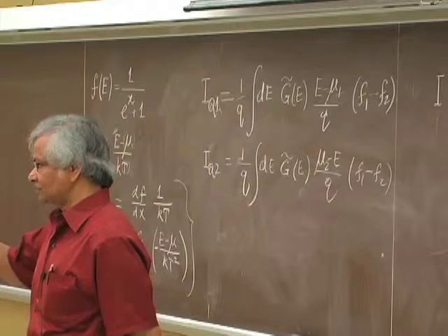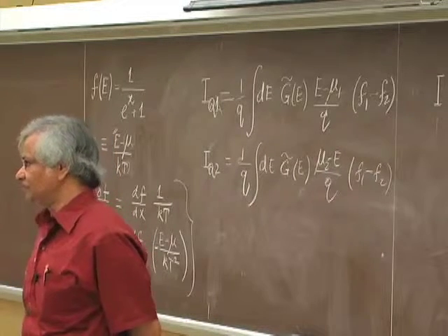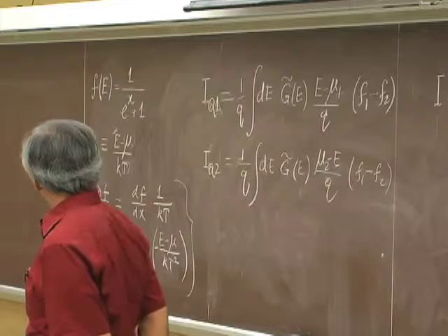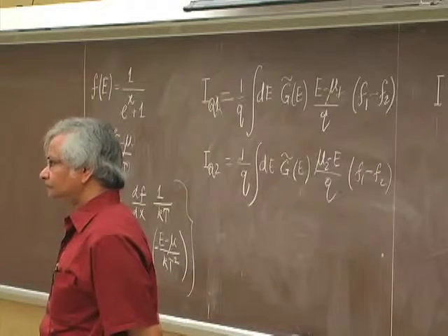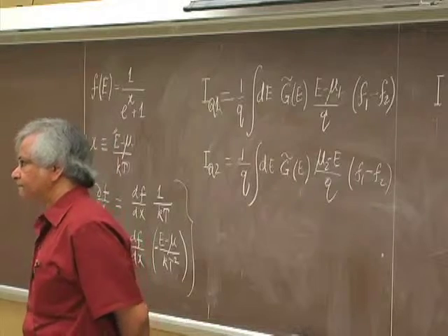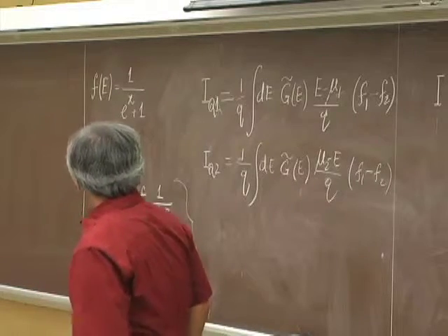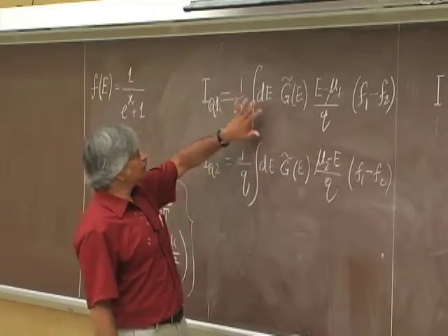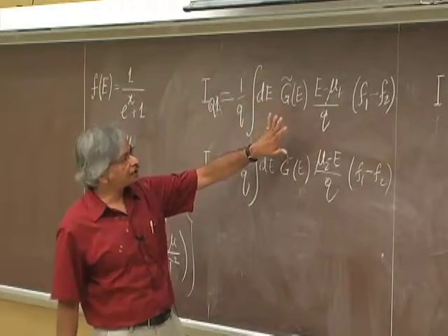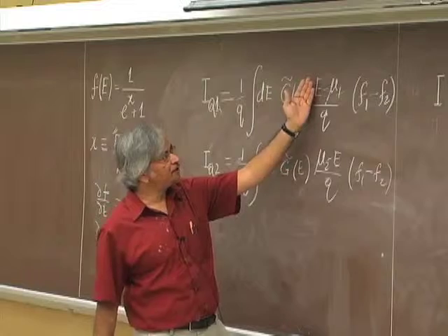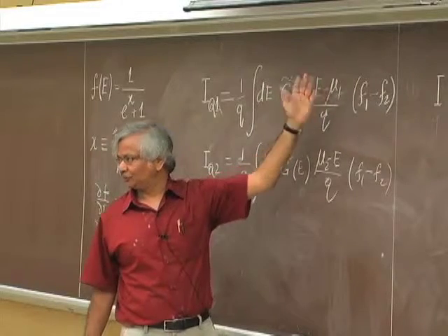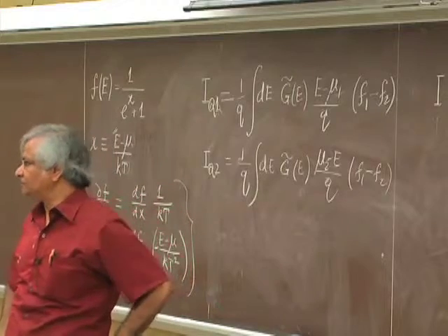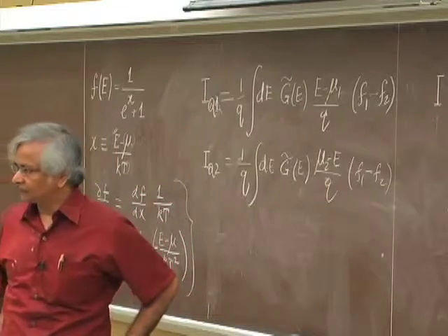But commercial devices are usually P-type materials and N-type materials in series. Because if it's very degenerate, then df/dE will be like a delta function. So if you replace E by EF or mu, it is 0. Right. So finally, in order to get a non-zero coefficient, there has to be an asymmetry between E less than mu and E greater than mu. Otherwise, as long as it's all symmetric, you won't get any Seebeck or Peltier, any of that.